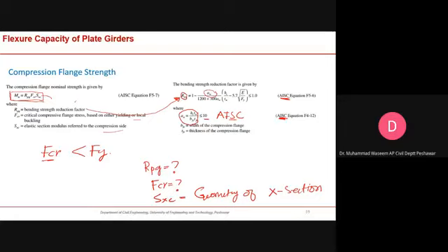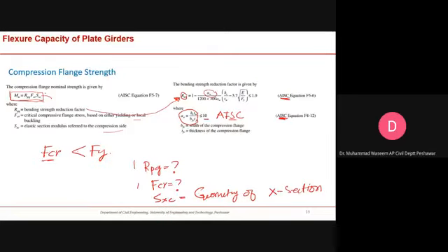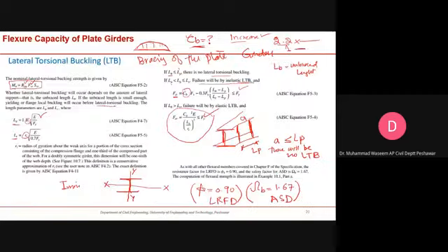Okay. Yeah. I know it is very difficult to absorb these values at the first go. Yes, sir. It took a while. So think over it. Okay. I will go very slowly, gradually. First limit state, you have calculated the bending moment using this equation. Second, you have calculated the bending moment using this equation. Then you compared these two equations. Whichever is giving you the least value, you will go for that value. You see here?